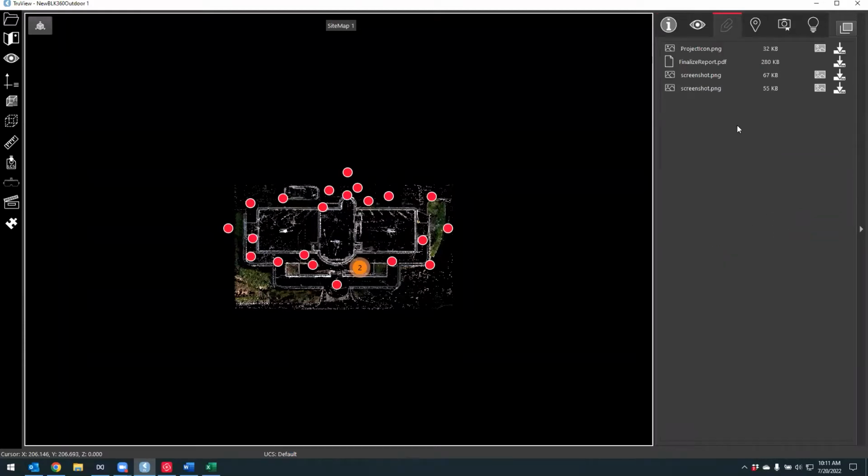This attachment thing is super important. I think it's often overlooked. This is going to be any of the annotations that you have. So if you were out using Field 360, and you're taking pictures and writing annotations while you're out in the field, it'll carry over in an LGS file. If you're doing annotations in Register 360, that'll carry over in an LGS file.